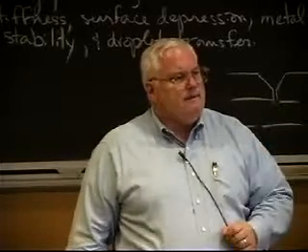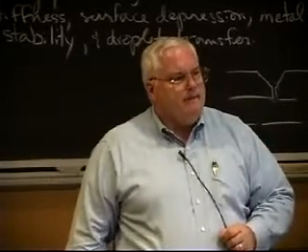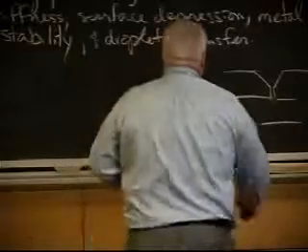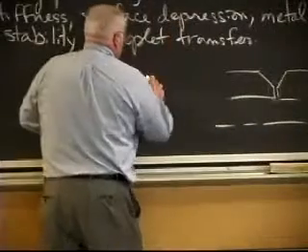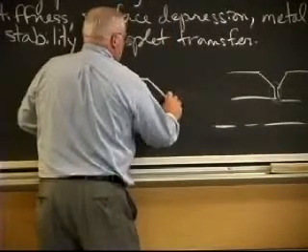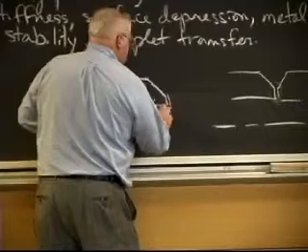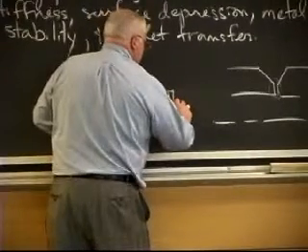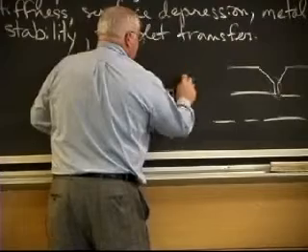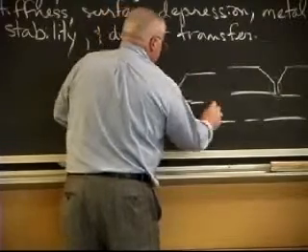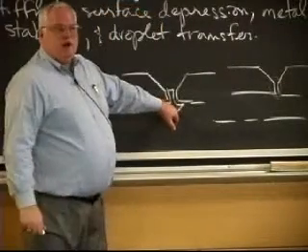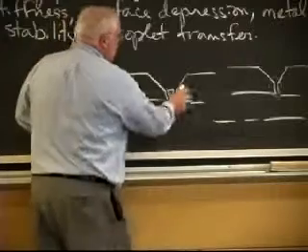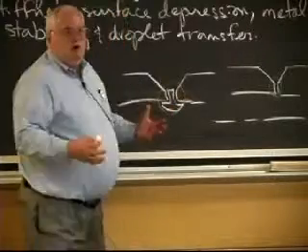Isn't there some type of pipe welding where you put an insert in there? Yeah, it's called an EB insert, for Electric Boat. The insert is just a piece of wire, and they roll it so it looks kind of nail-shaped. You put that little insert ring in there for the pipe, and now you go in with typically a gas tungsten arc and just melt the whole thing.